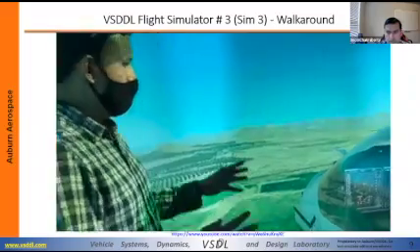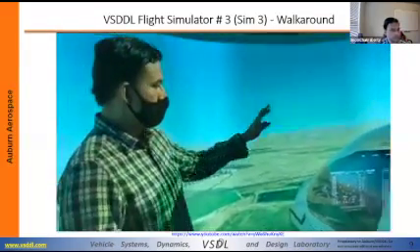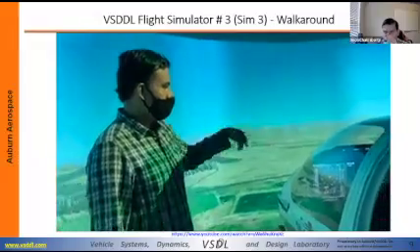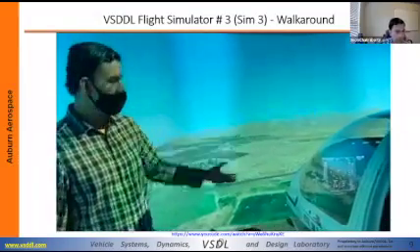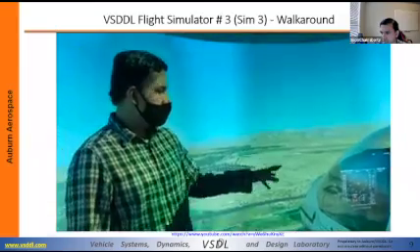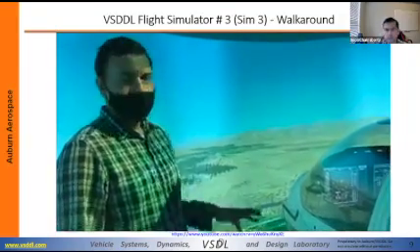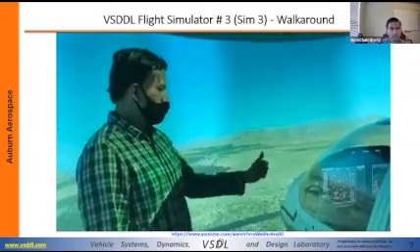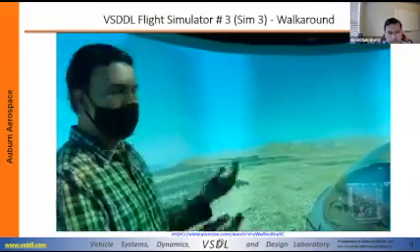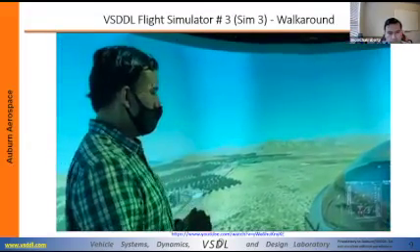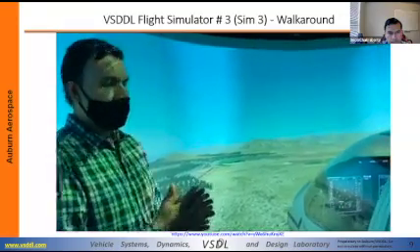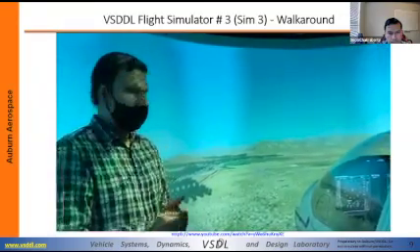We have full flexibility over the nature and appearance of the displays, over what is displayed and how the pilot can interact with those displays. We have full control over what the inceptor inputs map to. So they're just collected from here as normalized inceptor inputs, and depending on what control laws we've got, we have great freedom to decide how those control inputs interact with the aircraft flight control architecture.